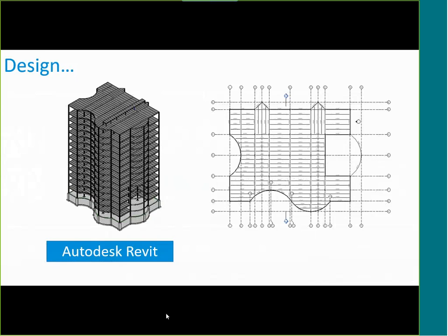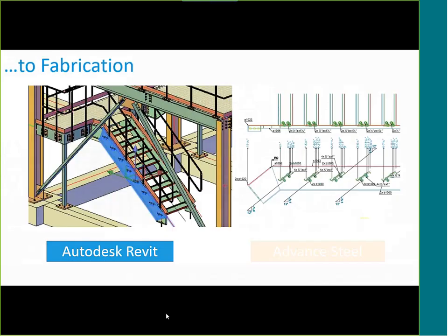And the fact that you can now add those detailed connections to Revit allows even more control over design by the structural engineers if they are doing it at that level. And so it could be that if you are working on almost a design build project, you might want to stay in Revit a little bit longer now and do some of those connections, because if there's a change, then you don't want to have to do all the translation back and forth. You want as much happening in Revit as you can. So it really depends on how your office wants to work in this particular case.